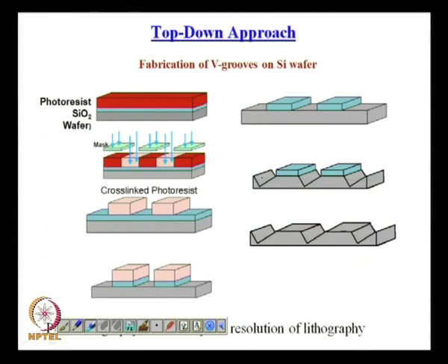So, the next step would be to use a silicon etch, which would be a concentrated KOH solution at elevated temperature, roughly about 85 degrees or so, and depending on the crystal planes it is going to etch. So, depending on which type of crystal, 100 or 110, whatever crystal of silicon that you are using, they are going to etch, and the two crystal planes will propagate and meet at a certain point, and the etch becomes self stopping.